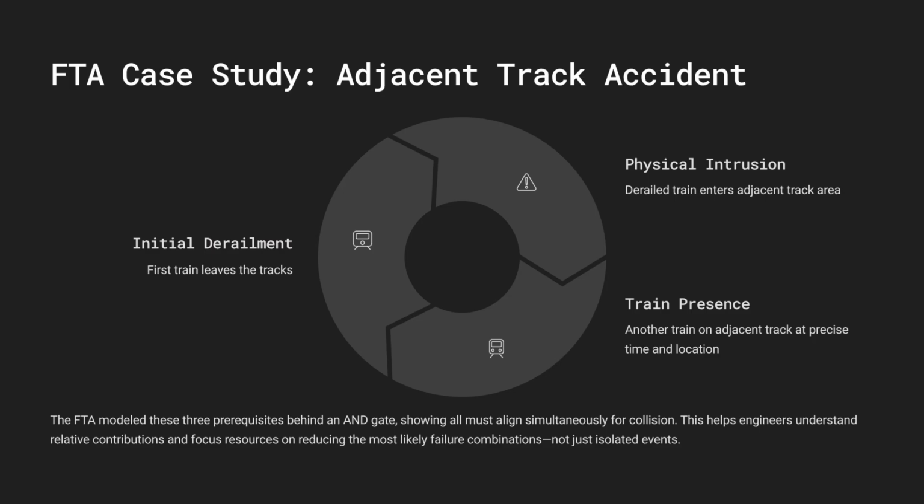This one's becoming more popular. It's a nice visual that combines FTA and another technique called event tree analysis. You put the main hazardous event, the thing you're worried about, in the center knot of the bow tie. On the left side, you basically have a fault tree showing all the causes, threats, and the barriers you put in place to prevent the event, like safety controls. So the left side is prevention. Right. And the right side maps out what happens if the event occurs anyway, the different potential consequences, and the barriers you have in place to mitigate those consequences, like emergency response, containment systems. So prevention on the left, mitigation on the right. Exactly. It gives a really neat single-picture overview of the whole risk management strategy, both proactive and reactive barriers.